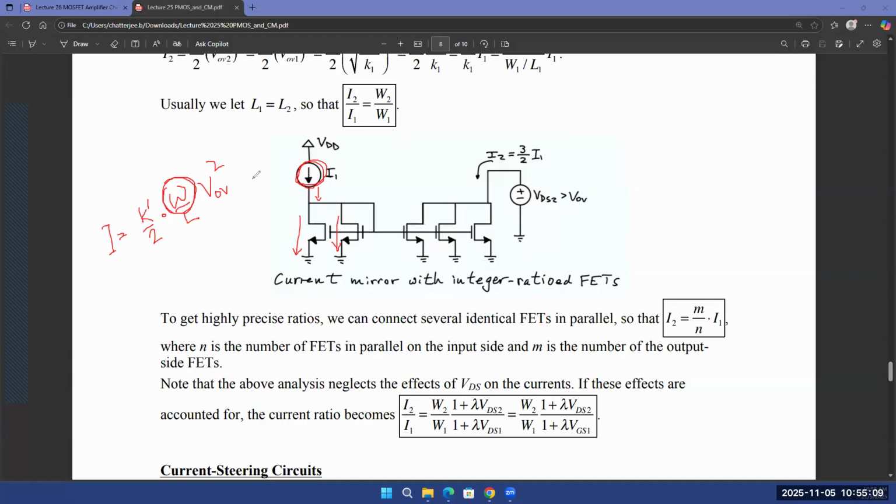Similarly, when you put two transistors in series, effectively your current is going to get halved, right? Because resistances will come in series. Two resistances in series, versus if you just had one resistance, your current is going to get halved. If you put two transistors in series, it may look like this. Let's say you have two NMOS transistors in series.